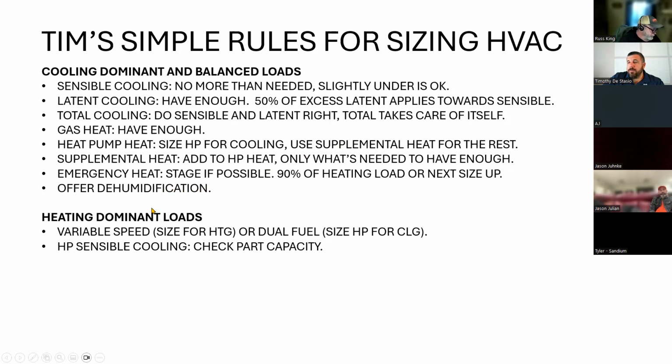Heating dominant loads, so colder climates, you're probably going to be using a variable speed heat pump. Use a cold climate heat pump. Just because it's a variable speed heat pump does not make it a cold climate heat pump. You want to make sure it's rated for that. It has things like a pan heater, so when it goes into defrost, your ice doesn't build up, and if it's a side discharge unit, it heats up your outdoor fan. It's got other technologies in there to make sure that it can actually run in those cold climates.